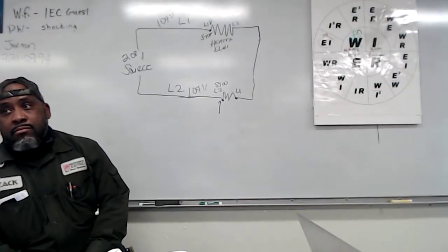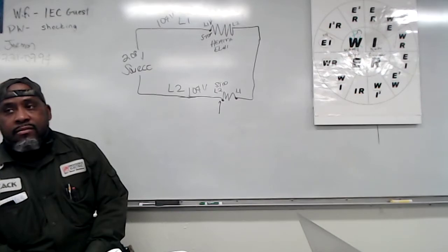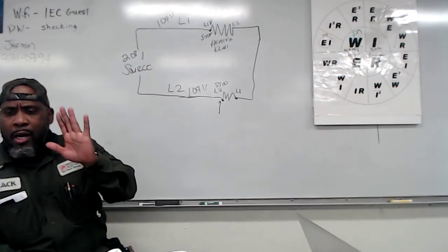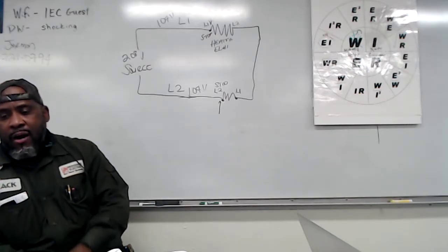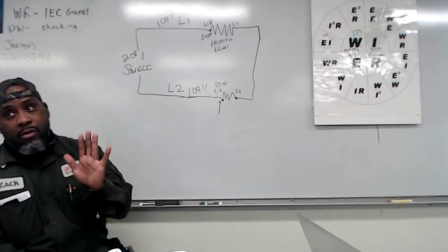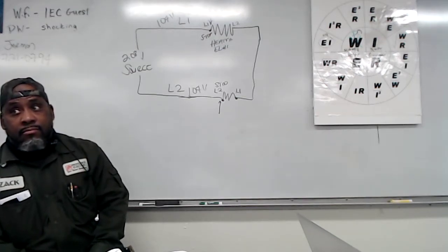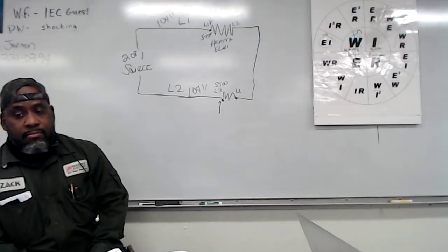That has to do with it being 3-phase, right? It's single phase, 220. It doesn't say 3-phase... I'm sorry, it does say it. It's a 3-phase 4-wire panel board, but we're only coming off with single phase. So there's not going to be anything between L1 on the bottom and L2 on the top.